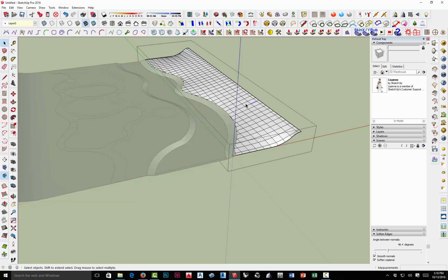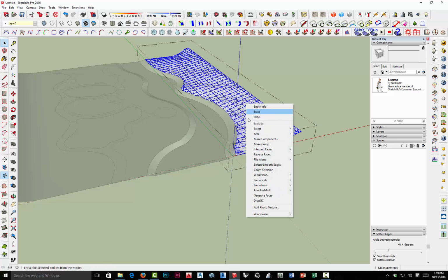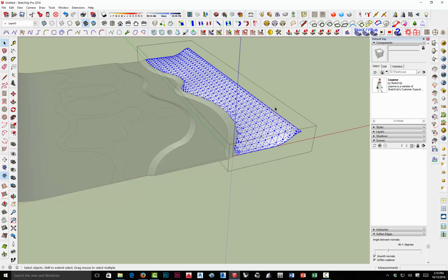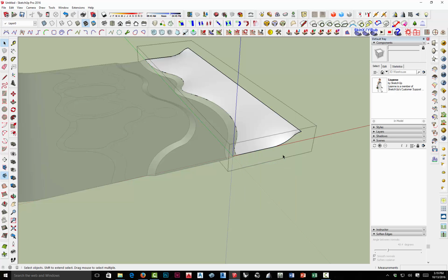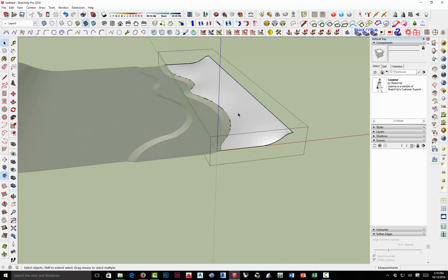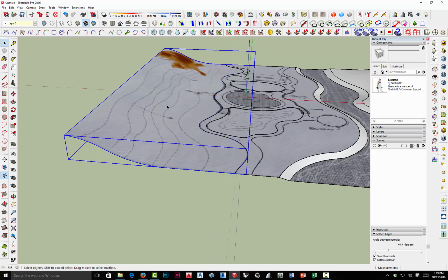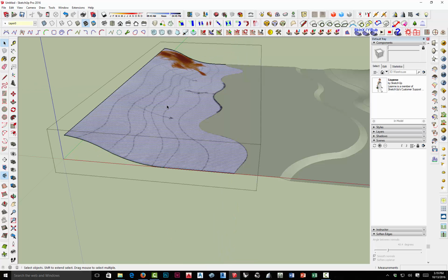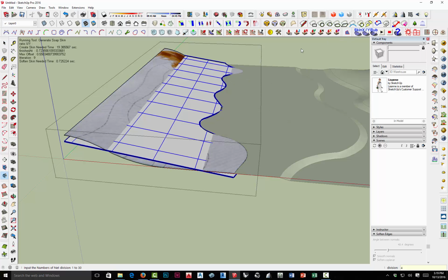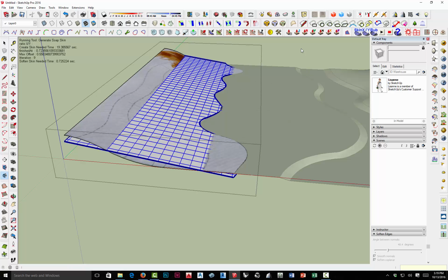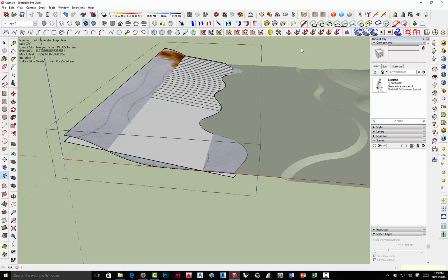Let's smooth it off too before we use Artisan. So I triple click, right click, soften smooth edges. Since I've already adjusted the settings, I don't really have to do anything else to it. So let's go over and do the other one, and then I'll come back and we'll work through the Artisan. I'm gonna come in here, open it up, double click only, soap skin, 40, enter to preview, enter to proceed.